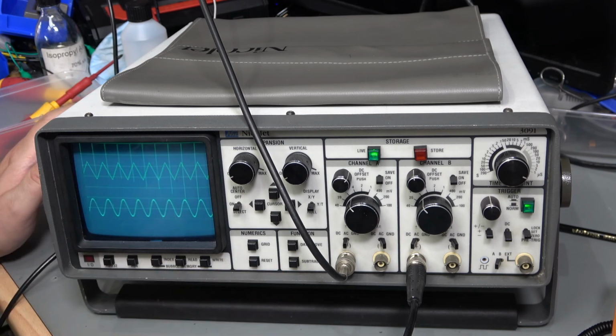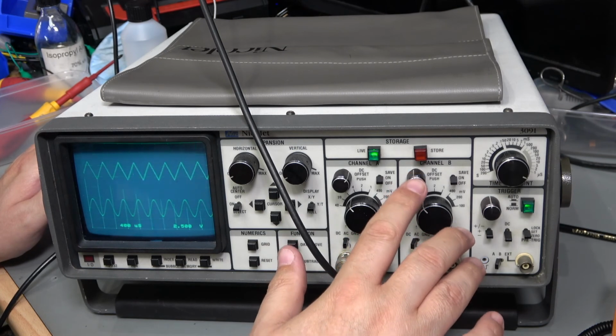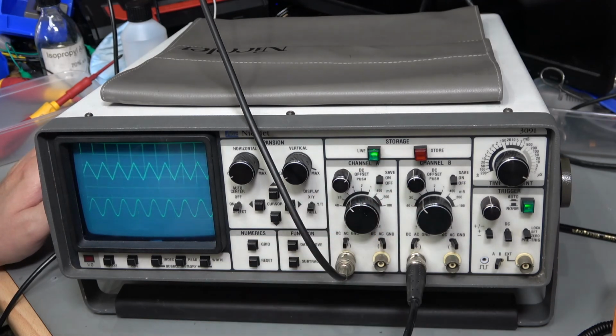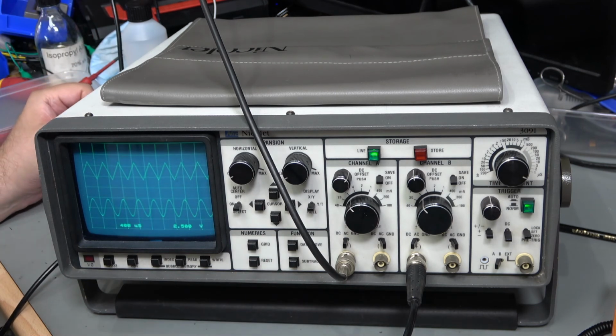It starts every time. There was a problem with the pot on channel B, the vertical offset pot, which is a very weird custom built device, and I looked at a replacement for that. I found a company that would do it, but it would actually cost me more to buy that one pot than the entire value of the device. So in the end I took the pot apart, found out how it worked, and effected a repair on it. Hopefully that repair will work well and last for a very, very long time.